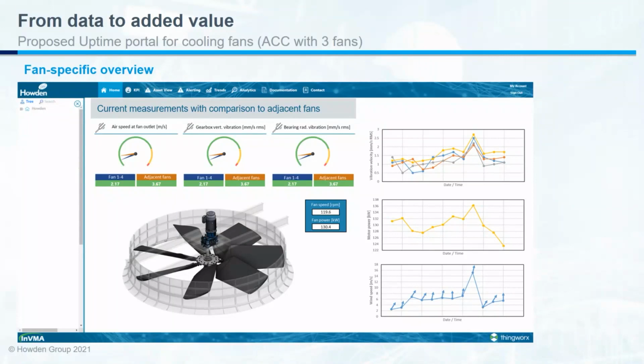And these can be related to, for example, blade passing frequencies or imbalance. It could be structural frequencies. So yeah, it will give deep insight of what's going on with this fan. And together with the simultaneous input of wind measurements, we can also link them and see, are these issues related to wind, or is there something else going on? So it will really give deep insights.